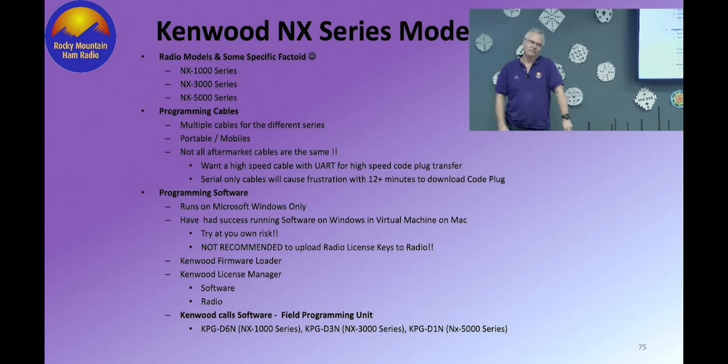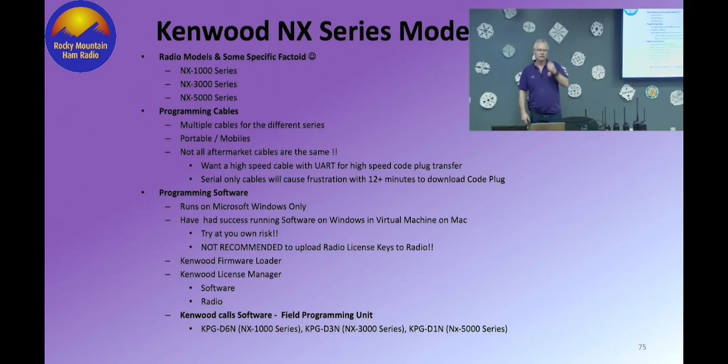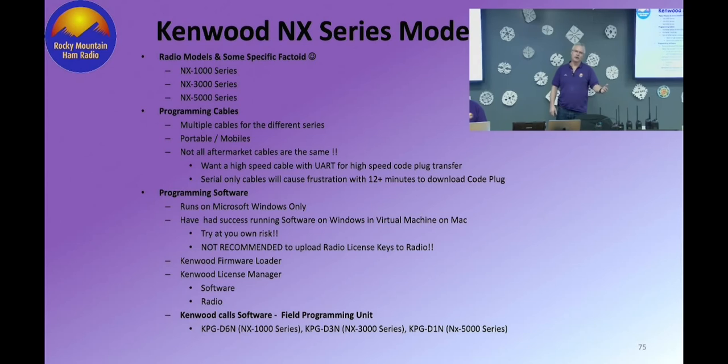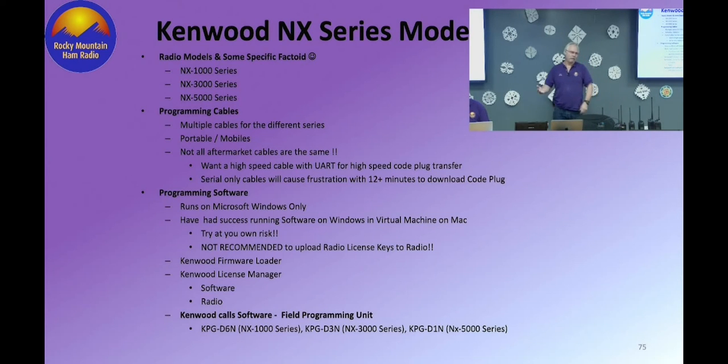Again, use it at your own risk. But the one thing that I don't recommend, I have never got it to work, never put a radio feature license from a virtual machine into the transceiver. It fails and you have a good chance of losing that feature. It's one thing if it's like a Bluetooth option that may be $10 or $11, but if it's a P25 option that's several $100s, you really don't want to lose that. So that's just a recommendation that I get from firsthand experience.